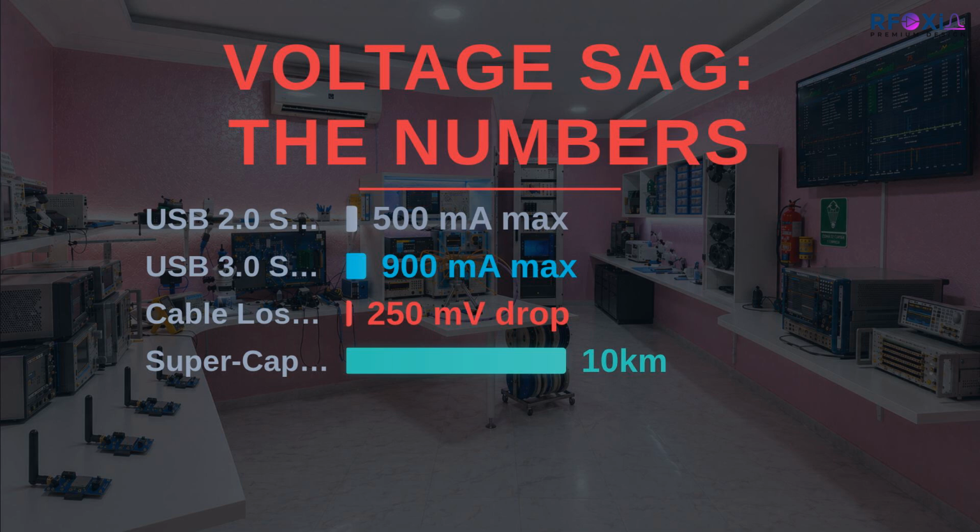Ground noise is the second mechanism. When multiple devices share a USB ground rail, your programmer, your target board, your logic analyzer, your laptop chassis ground, you create conditions for ground loops. A ground loop means that what you think is 0 volts at the programmer is not actually 0 volts relative to the target device's ground reference. A difference of 50 to 100 millivolts in the ground reference can be enough to cause SWD communication errors. The programmer interprets this as a protocol failure, reports a generic flash error, and you go looking for the wrong thing.